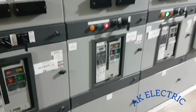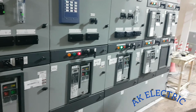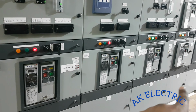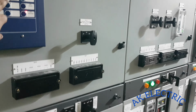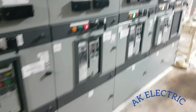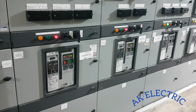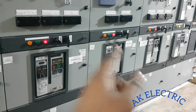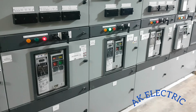So now we will give power supply to incomer 2 by turning incomer 2 supply on. Now again we have to go to manual mode. Everything here we have to cross check whether it is in manual mode or not. Then we have to put it in tie breaker. Now we will close incomer 2 and the tie will open automatically. Now incomer 2 is closed, and the tie will trip automatically. So this is the ATS function.